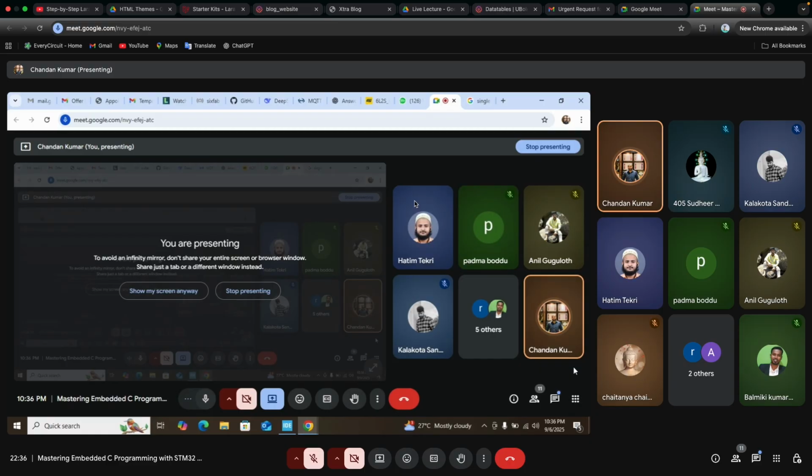Then comes the fifth part, data bytes. Till now we have started the condition, we have selected our slave using the slave address, and we have selected whether the master wants to read or write. Then the receiver has already initiated a bit which tells whether it has acknowledged or not acknowledged the transmission. Then comes the fifth part, the data byte. The data byte is the same in all communication. It is the data which we want to transmit between master and slave.